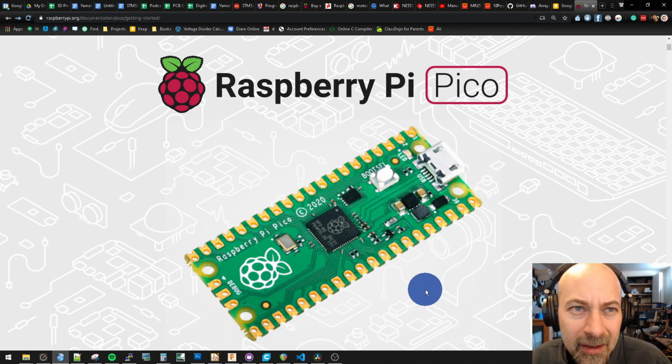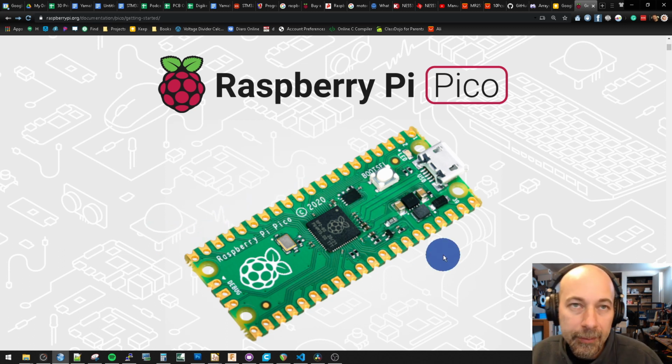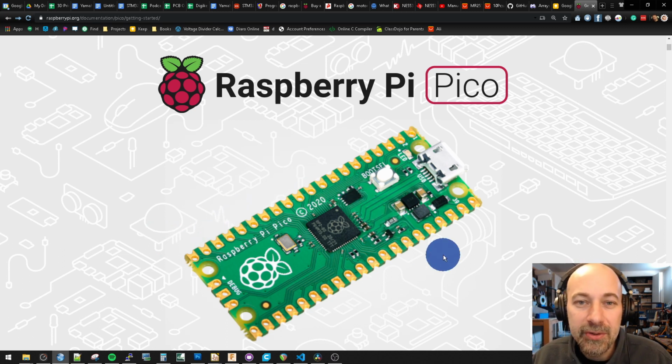I don't love that. I don't like headers. What this means is you could use surface mount. You could just have pads, little square pads, and you can just set this thing down and solder directly to the board. And so that means you could do this with mass production, for example, or at least more mass production than most of us deal with.